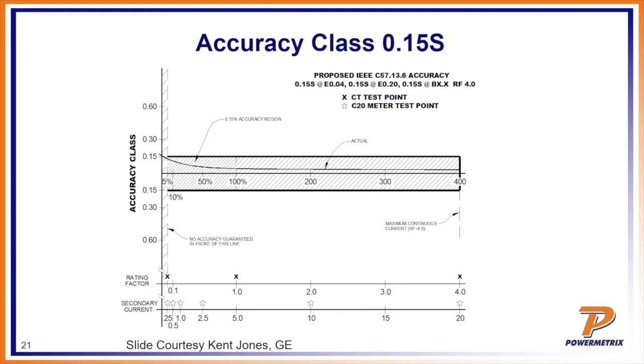Also, when we get to the point where we're actually testing the transformer, we're using a probe, let's say like a flexible current probe, or a sensor link probe, and that will decrease the accuracy as well, because a probe is meant for versatility, but you have the trade-off of inaccuracy when you have to position the probe to get into the cabinet or around the conductor to get a measurement.